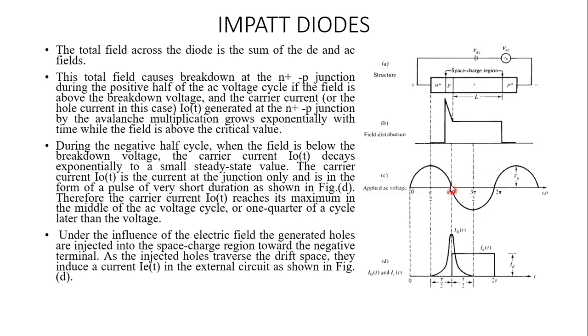Now this is the noise, which should have random variation of voltage and time period. But since we are making use of this as an oscillator, of course it will have a fixed frequency with a smooth waveform. So out of the multiple frequencies of the noise, one particular frequency is chosen. Because here it's not the complete circuitry, but if you make a tank circuit, then out of the frequencies required for oscillation, the one frequency which we want to exist, or want to collect as output, is selected.